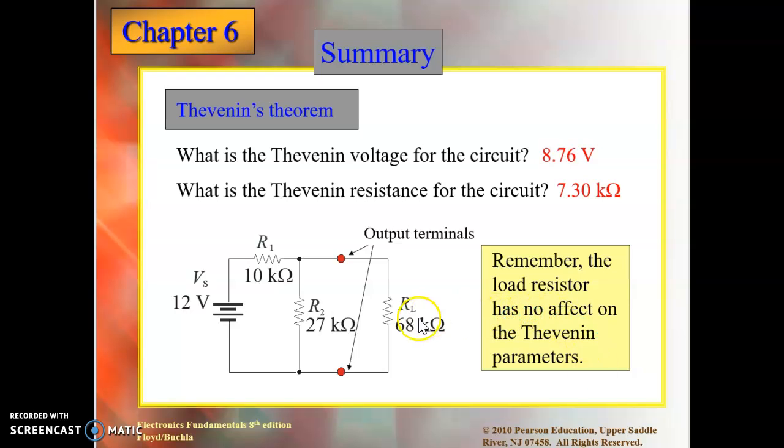So right here we have a simple Thevenin example, and they are giving us a combination circuit, and they are saying Thevenize the circuit from this point. So from this point to the left, we are going to Thevenize to see how this RL is going to see these circuits. So the first step before we move on is to remove the RL.